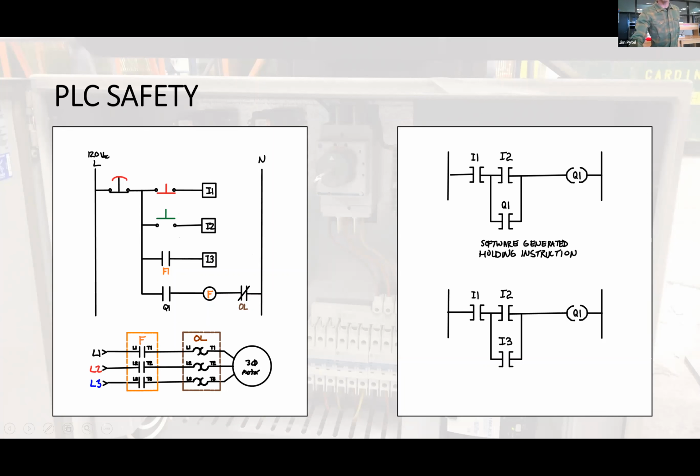Okay, there's a fundamental difference. Before going on with the explanation, F1 is a normally open auxiliary contact associated with the F contactor. When the F contactor is closed, the motor starts turning, but additionally, the F1 auxiliary contact closes.